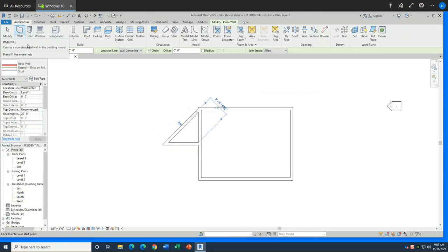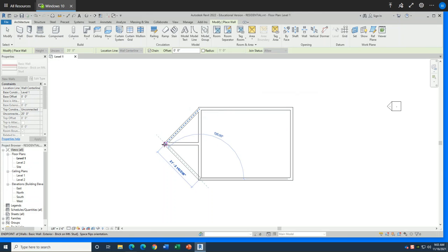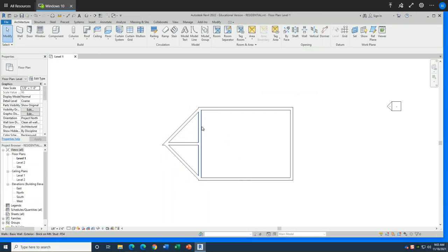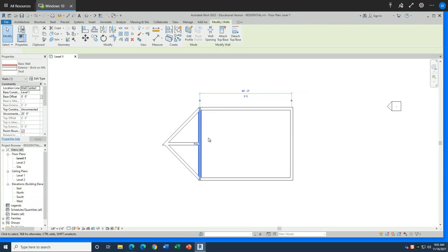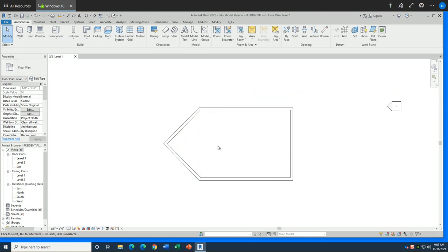And I'm going to try maybe the second wall option here, and go to the corner again, like that. Now we press the escape key. Now I'm going to erase one of the walls, and I will go with the wall command again, for the other end, architectural wall.